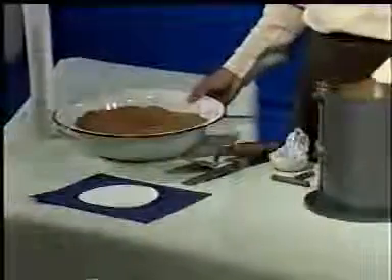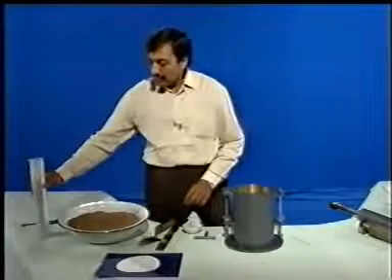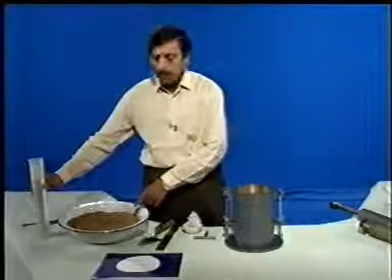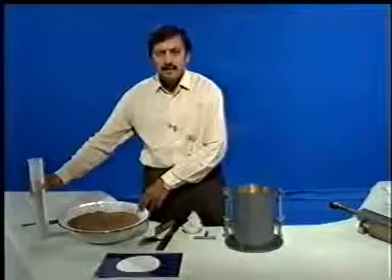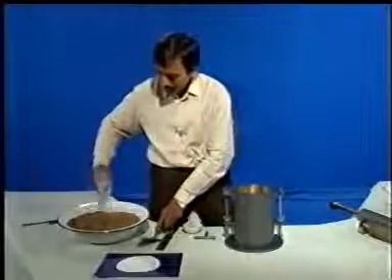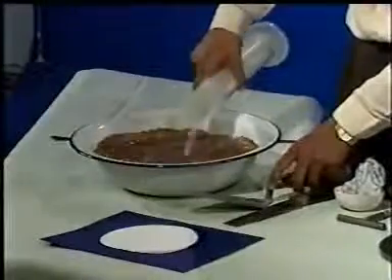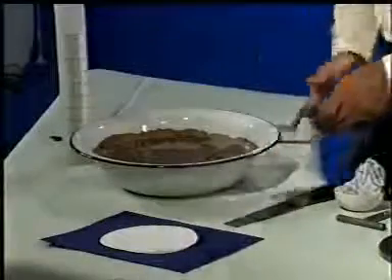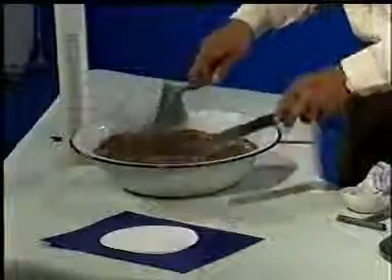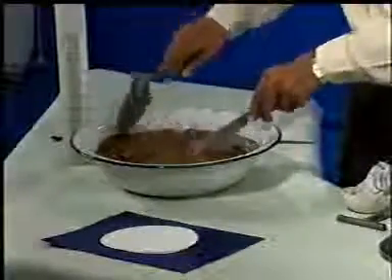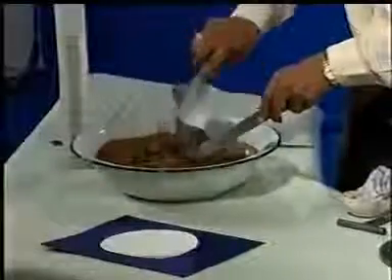Now take about 5 kg of the soil, passing 20 mm sieve. To the soil, mix a predetermined quantity of water such that the water content of the soil is either equal to the OMC or equal to the field moisture content, as the case may be. Mix water and soil thoroughly so as to prepare a mix of uniform consistency.